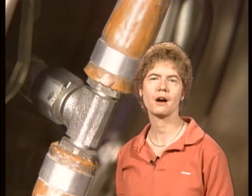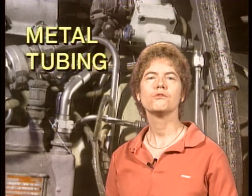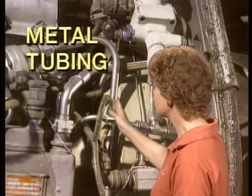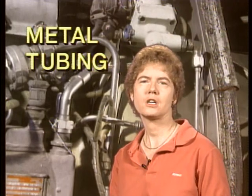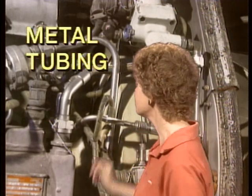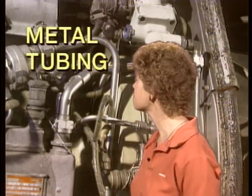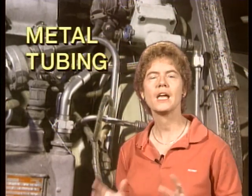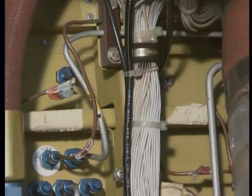Now let's talk about metal tubing. In a metal tubing installation, you do not want the tubing to run straight. You want to have a bend in it because tension in it is not desirable. Tension in metal tubing is undesirable because pressurization, when it gets the pressure of the fluid in it, will make it expand and shift, and that will create problems if it's under tension.